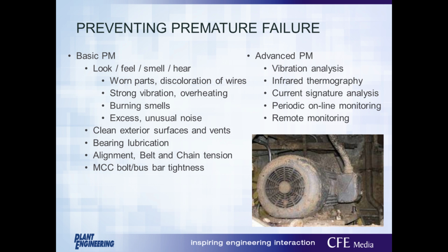You do want to keep the exterior surfaces and cooling passages clean and clear. Keep your bearings properly lubricated. Keep the motor alignment very good, and any belts or chains at the proper tension amounts. Also, keep the motor terminal lugs at the proper tightness, and on down the line at your bus bar or motor control center, keep those at the proper tightness as well. What you don't want is to have your motor terminals or motor wires falling out of a VFD, for example.